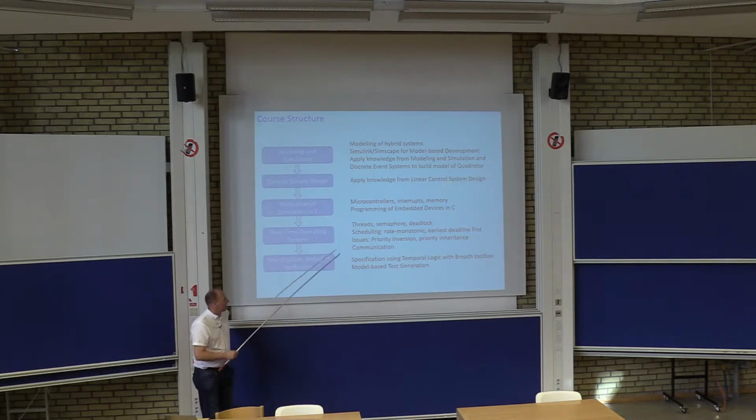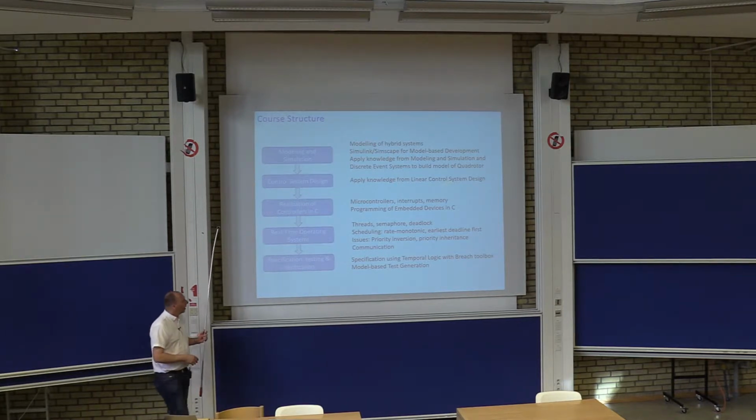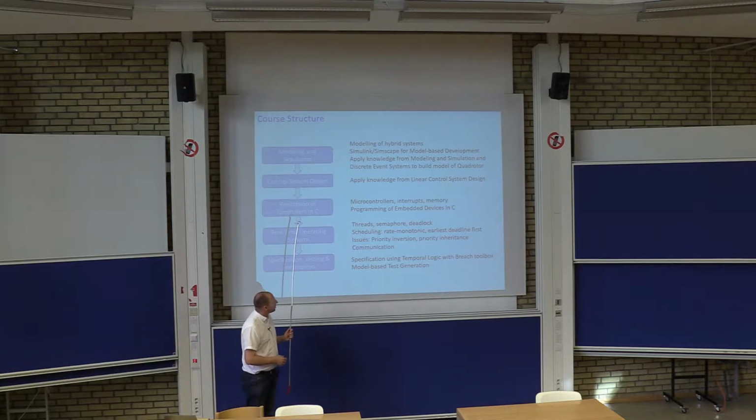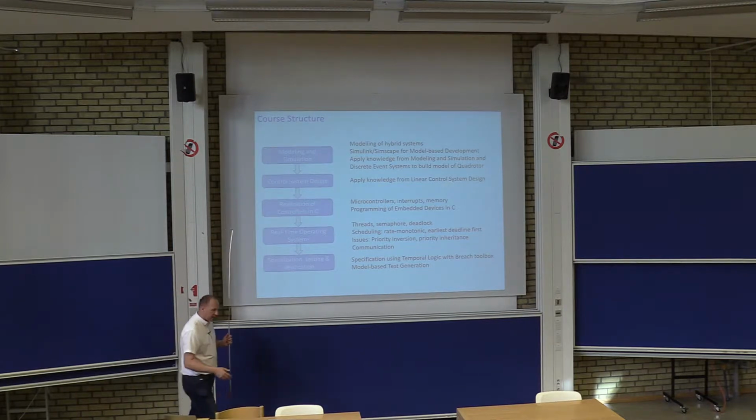Of course, in most systems, like Sadir mentioned in the SSY190, there are, what did he say, 120 ECUs, something like that, and you have a number of different networks. So of course communication is a very important problem as well. But we talked about the problems that communication leads to. You have the delay, you don't know when to access the network, so that causes both jitter and latency, and that will affect the control performance.